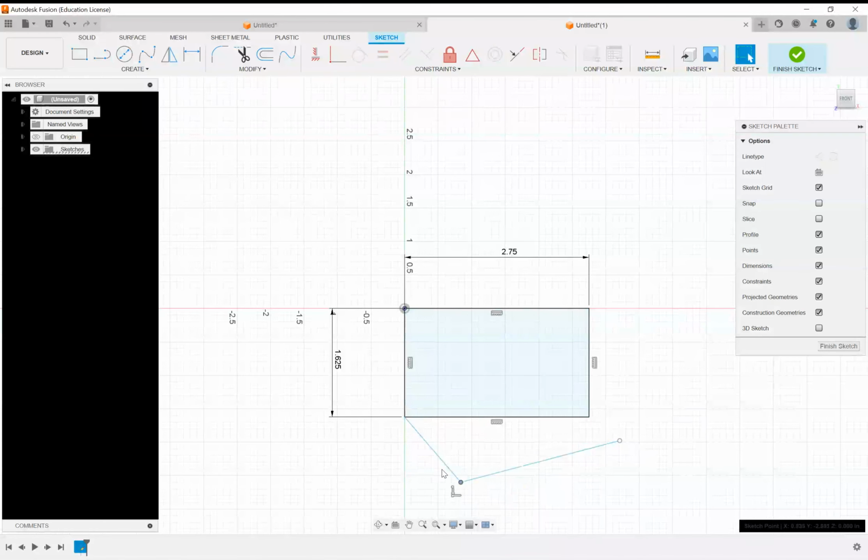So we've got this attached to one corner, right? But I can move this point. I can move this point. And if you notice, this sketch area is fully closed off, and then it highlights a light blue. That's important if you want to be able to make this into 3D geometry, that you have that enclosed. Notice this area down here is open. We got to make that so this point and this point connect.